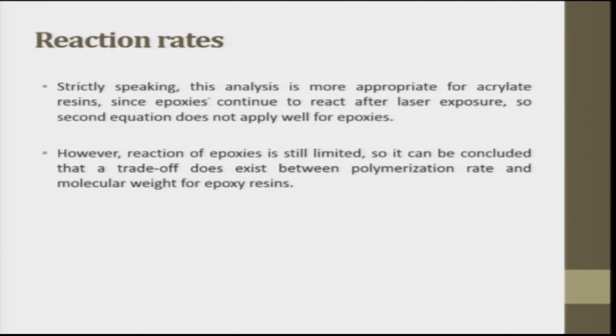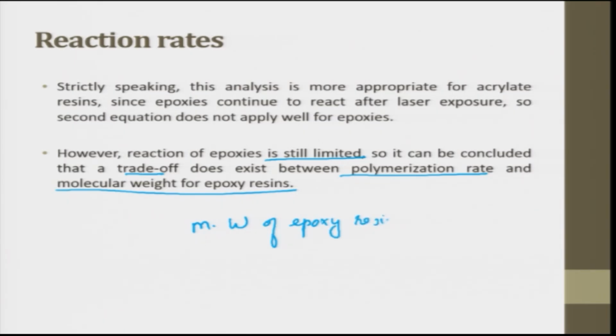So, strictly speaking, this analysis is more appropriate for acrylate resin since epoxy continues to react after laser exposure. So, the second equation does not apply well for epoxies. However, the reaction of the epoxies is still limited. So, it can be concluded that a trade-off does exist between polymerization rate and the molecular weight of the epoxy resin. So, the molecular weight of epoxy resin is proportional to polymerization rate.